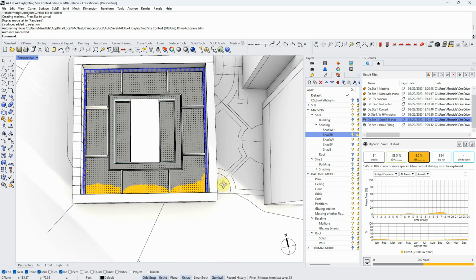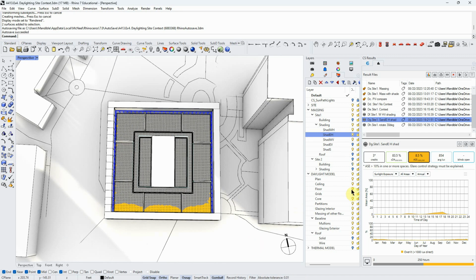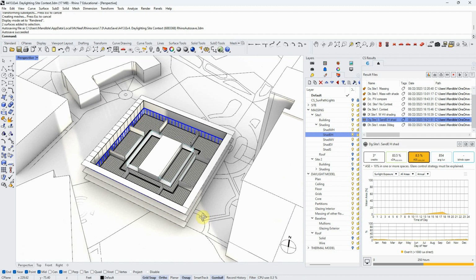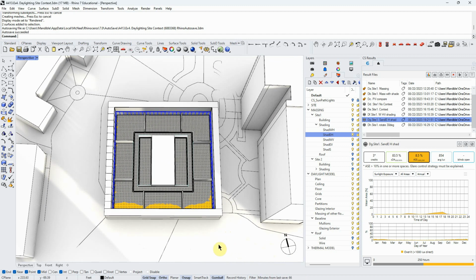So at this point, I've got a really good daylighting approach. I've got my full 3 points in LEED 4.1. Again, we're not just chasing points, but these are good indications that we're meeting some goals that we set for ourselves, which is daylight autonomy. So we're over 75%, so we have very good daylight autonomy, and we are less than 10% on average for being overlit. So this is a good design. Not saying that architecturally it's what we want to do, but we have some ideas now, right?